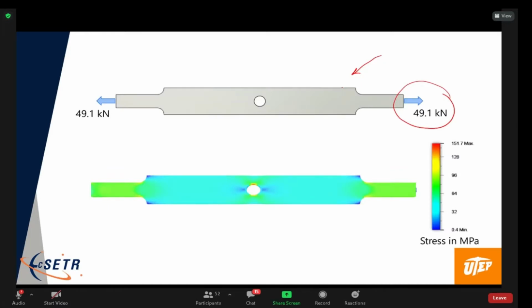So if you wanted to solve something like this using finite elements, really your best bet is to assume this force, right? See what stresses you get, and then figure out what's the margin, what's the factor of safety between the peak stress that you find in the finite element simulation and your allowable stress. If it's 49.1, then you know your load has to be 49.1 times the load that you apply. So actually, I think I did do that in the finite element too, just to check. I cheated here a little bit and I put directly the 49.1 on here, okay?